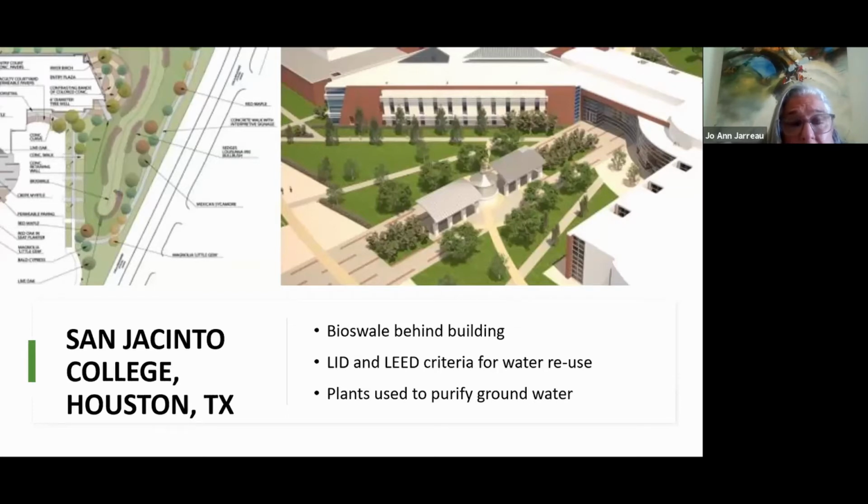pond area. Different times of the year it would be higher and lower, but in that area we really did have a bioswale that functioned to drain most of that area to a stormwater sewer. We used the bioswale and the rain gardens in the bottom of the detention area to filter the pollutants that were coming from the entire site.